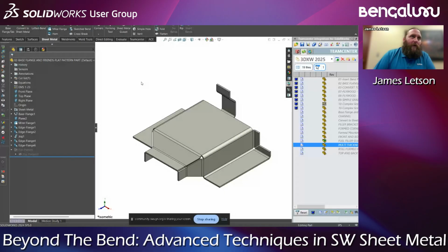Any fabrication shop that has been around for any period of time is most likely going to have all of that already figured out, right? So if you are a contracted employee and you are sending material to a fab shop, I would reach out to that fab shop and figure out what their bend allowances and K factors are.